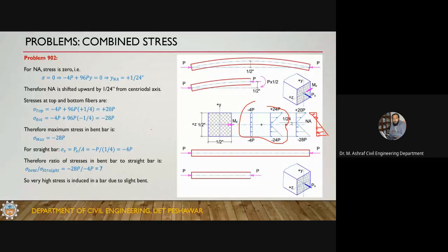While you are casting the concrete, they come under stress, and there might be some serious problem. So what if your contractor is an intelligent guy and has some engineering sense? Then he combines the vertical elements with a horizontal strip, and in this way he can control the lateral movement of the member, and he can control the excessive stresses produced in the vertical supports. This is a very good example.